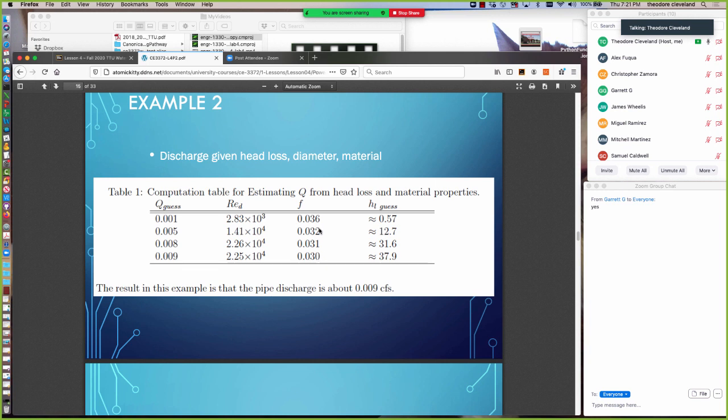We're getting to the point where the friction factor is not changing very much because of our eye's inability to read the chart. So there's a certain resolution at which we can't resolve. As the Reynolds number moves a little bit, there's no apparent change in friction factor, which is likely not true, but that's a limitation of the chart.